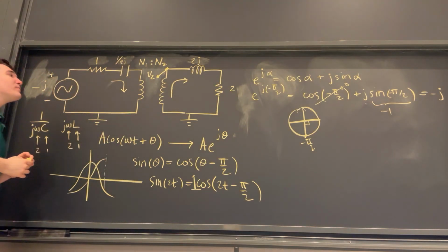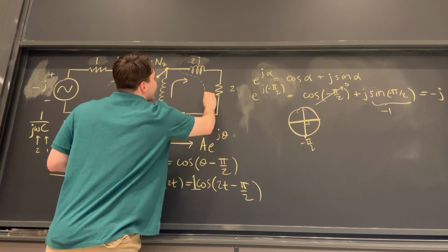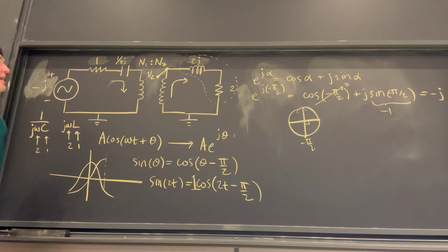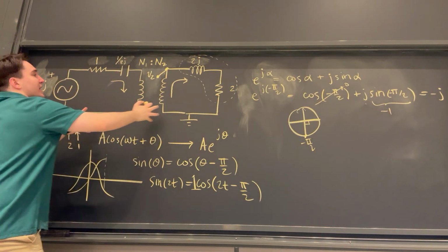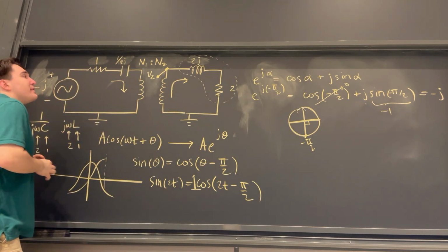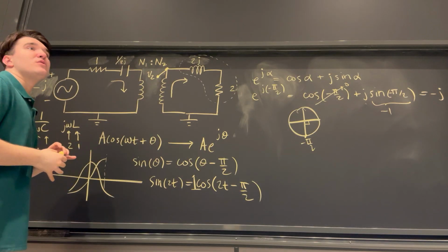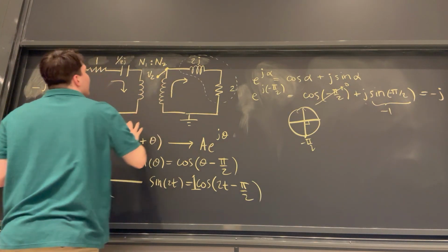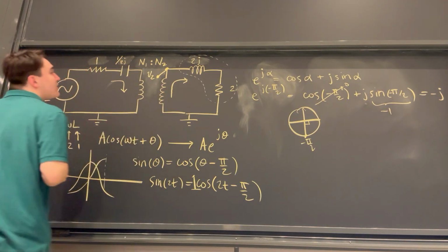The way that we normally do that is we are actually going to take the impedance that we see on that side of the circuit, and we're going to shift it over to this side of the circuit, and manipulate its value so that the whole circuit will be sort of equivalent to what it once was, but it will have the effect of getting rid of these transformer coils in the middle here.